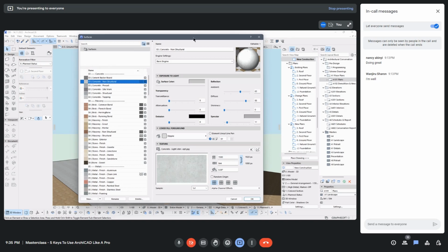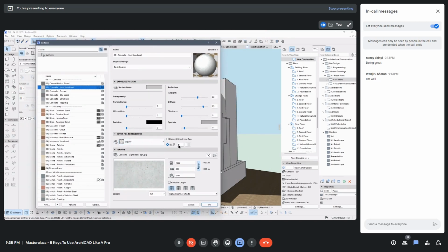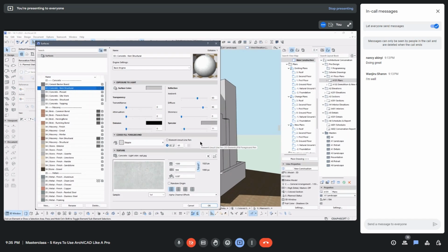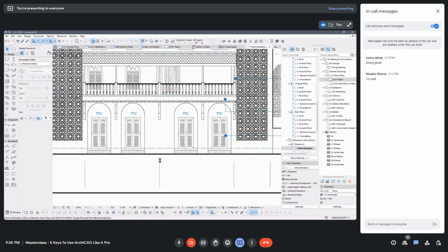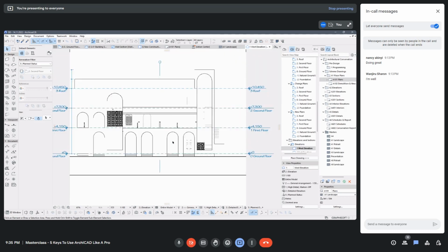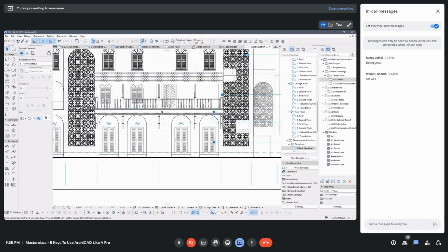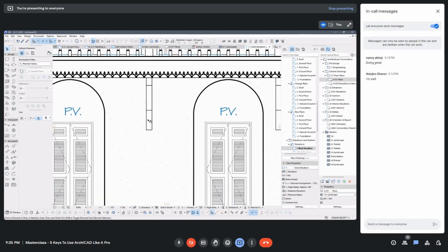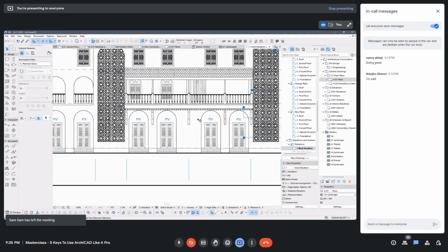if we choose, or rather in elevation views, in elevation and section views. Up until ArchiCAD 25, if you were to choose to display elevation in color, you could only show either the surface color with vectorial hatching or not. If you look closely at this surface here, you'll see that there's some slight stippling.